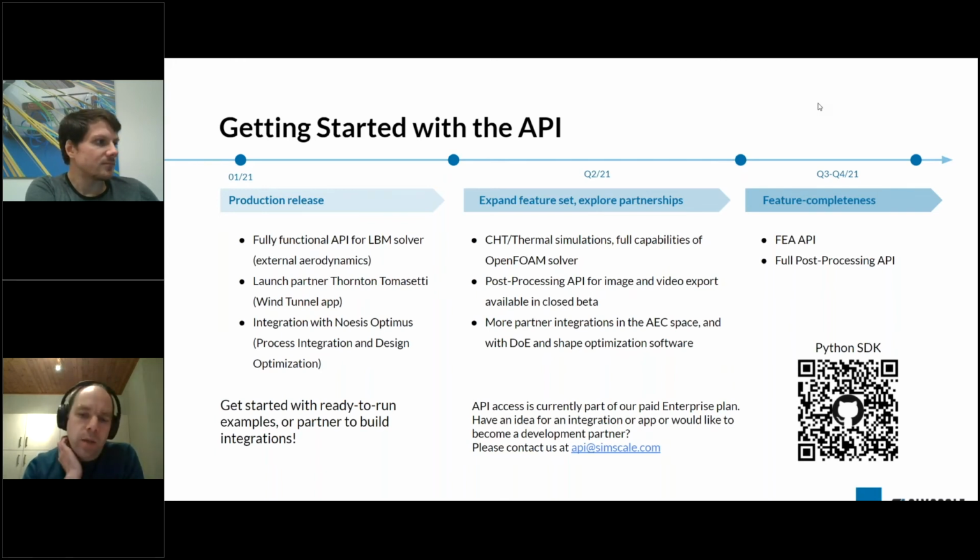On the other hand, I'm quite interested in the optimization actually, because with the whole Rhino and Grasshopper environment, you could also write smaller applications, but much more granular and geared towards that optimization. So you could actually run a building shape optimization of, let's say, reducing harsh wind conditions on the streets, or reducing the loading on a building, right? Make it respond better, that sort of thing. Within Grasshopper, you could run a genetic algorithm where you run CFD simulations in the background and get the results, evaluate the metrics, and based on that, change the geometry and run it again, right?